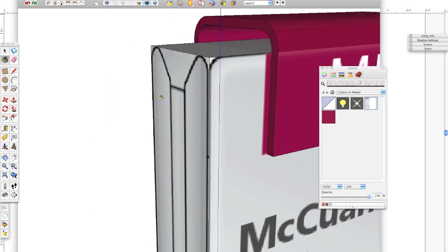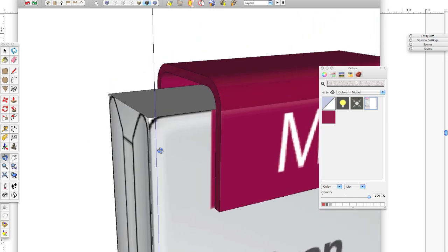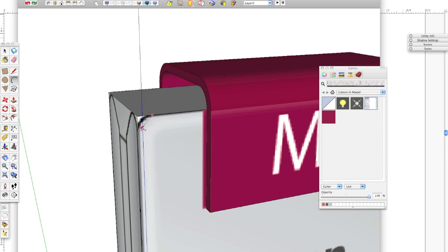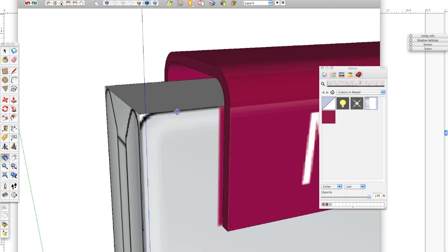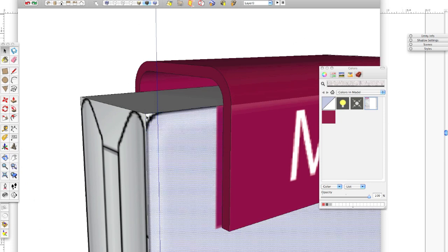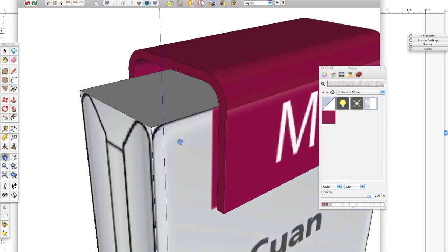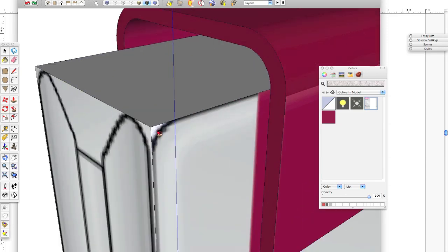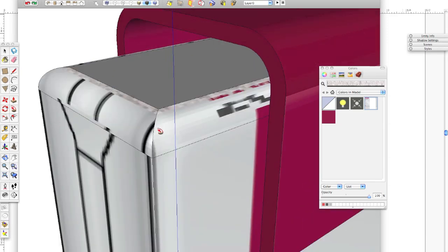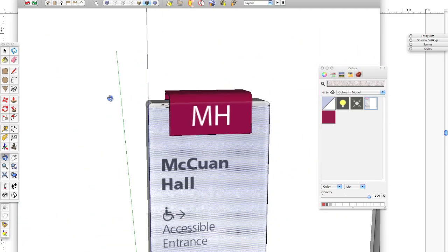I know there's a lot more detail to how the side piece works here, but just for aesthetics and simplicity, I'm just going to create a little arc here. So you see how it breaks that profile onto the side like that. And then if I click on the top surface, which essentially selects or highlights the edges that make up that surface, I can then click the Follow Me tool, and I can single click on this area here, and it'll follow all the edges for that corner.